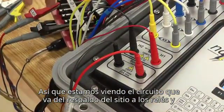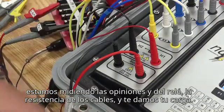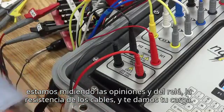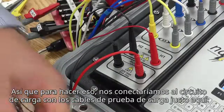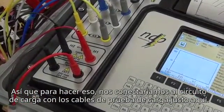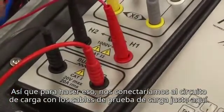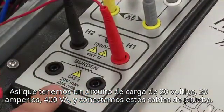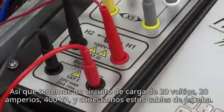So we're looking at the circuit that's going from the CT back to the relays, and we're measuring the impedance of the relay, the cable resistance, and we're giving you your burden. To do that, we would connect to the burden circuit with the burden test leads right here. So we have a burden circuit of 20 volts, 20 amps, 400 VA, and we connect these test leads.